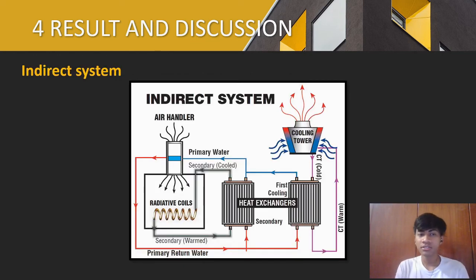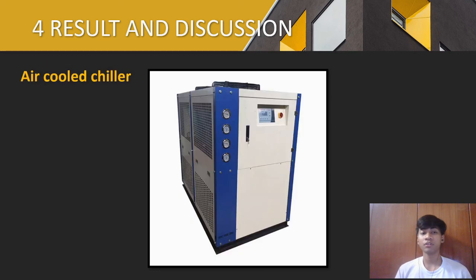For the air conditioner system, we agreed to use indirect expansion, where the refrigerant cycle works indirectly to absorb the heat from the refrigerated space and release the heat to the environment. This system is better known as a chilled water system. Chilled water works as a refrigerant to absorb the heat. Heat is absorbed by the refrigerant cycle in the evaporator. This building is a private office, that's why we choose the indirect system.